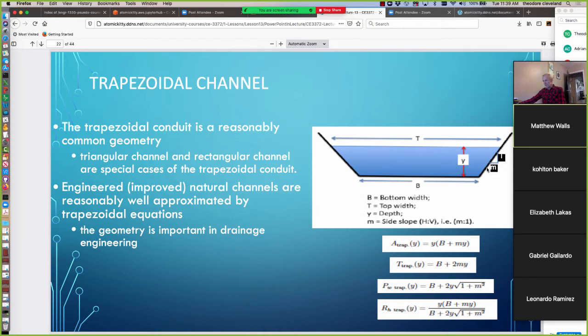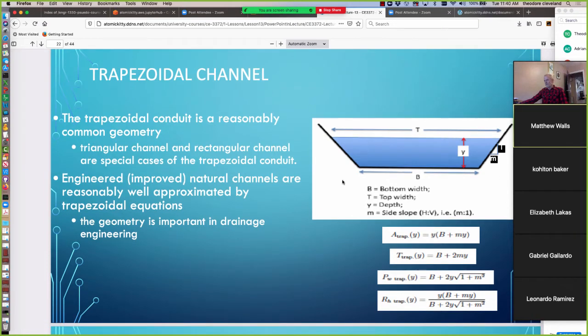And the 6 is not a hydraulic choice. That happens to be the side slope that the FHWA has determined is something called traffic safe. What traffic safe means is you can take your pickup truck at 85 miles an hour and drive into a 6 to 1 side slope and live through the resulting accident. And in a good world, you might even get to the other side of it and the vehicle still be operable. So let's examine the hydraulics of the trapezoidal channel.